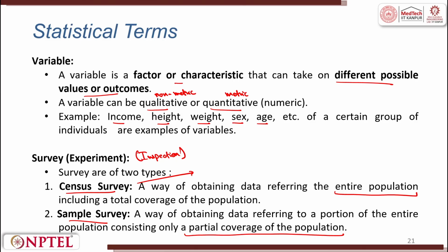Sample survey has its advantages. The time spent on the overall inspection is lesser. In census survey, sometimes destructive testing is involved. For example, if you need to see the internal properties of the nozzle, you might have to cut the nozzle and examine its internal properties using multiple techniques. That is destructive testing. If you do it for all of them, you would be left with nothing. All the 100 nozzles will be destroyed. In the sample survey, you destroy only 5 nozzles to test what the internal material characteristics of the other 95 remaining pieces are likely to be. So that is sample survey.